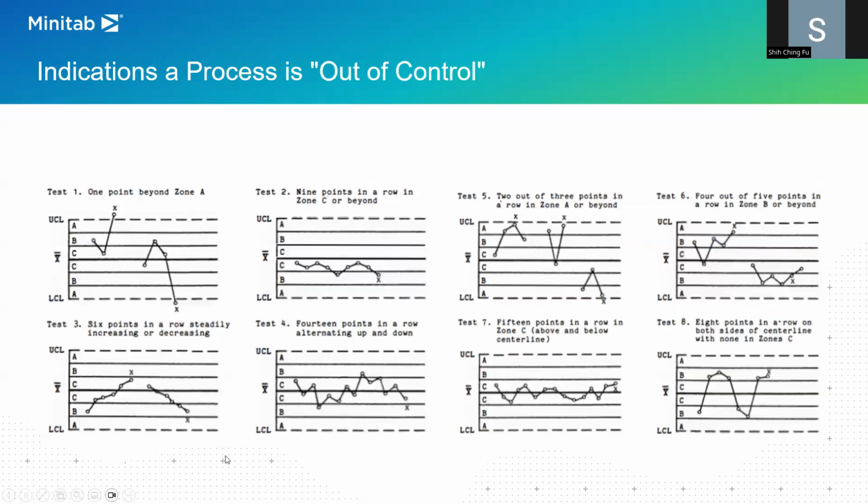Real-time SPC can detect assignable causes like some patterns. These are the rules, the Nelson rules. We'll talk about different patterns, just quickly going through a few of them. For example, one dot outside 3 standard deviations. By chance, it's only 3 out of 1,000. Very low chance. We probably say it's unlikely to be due to random stuff. It could be due to some assignable causes.